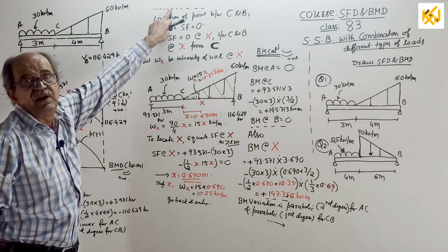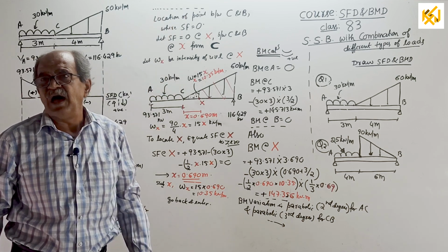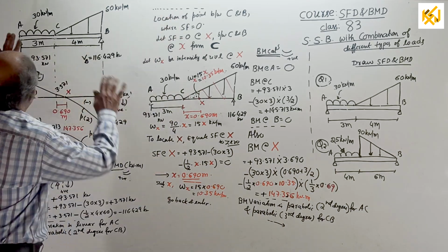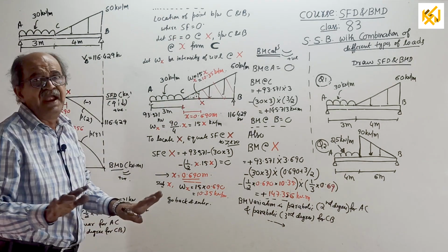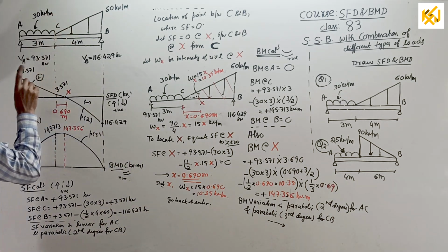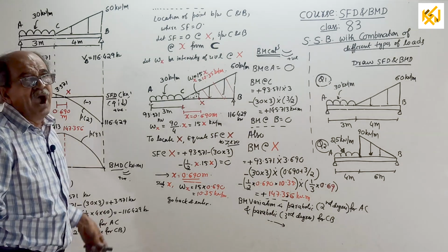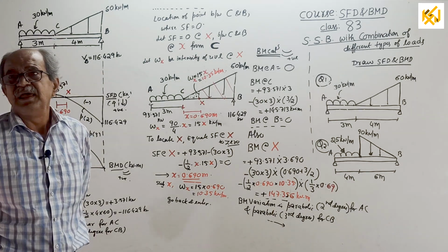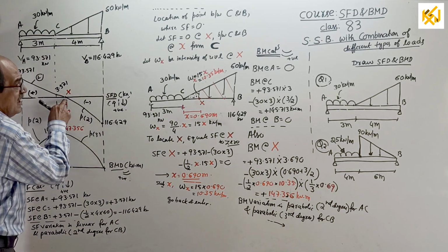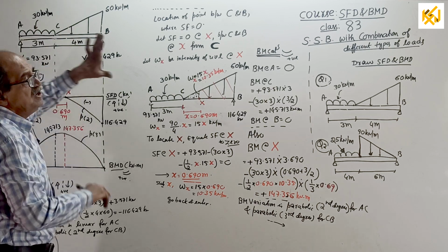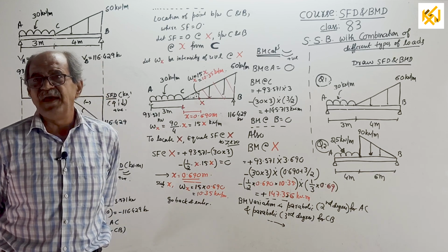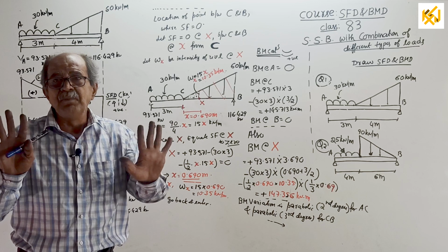Now, some statements, dash, dash, dash, mean in my class I am dictating something. Those who are serious should note down. Go back and draw the shear force diagram with all the principles I told just now. Observe the shear force diagram and check: is there any point where the SFD crosses the baseline, and decide known point or unknown point? See, the SFD will cross the baseline here. It is an unknown point, so that point you have to locate. Why, I cannot answer now. This is the last time I will tell, next time I will not tell this one. This point, permanently, now.